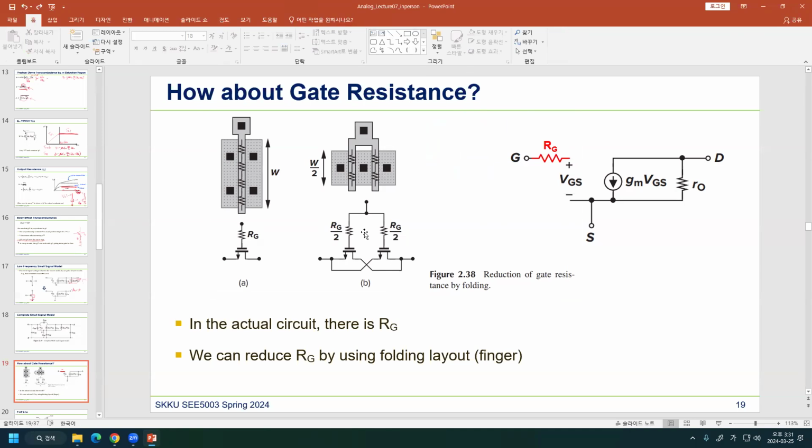Well, MOSFET is usually pre-designed, so we call it a P cell. They give us a pre-designed MOSFET, and then in layout we just put some W, or how many fingers you want, and how large the length is, something like that. But we still have a choice.